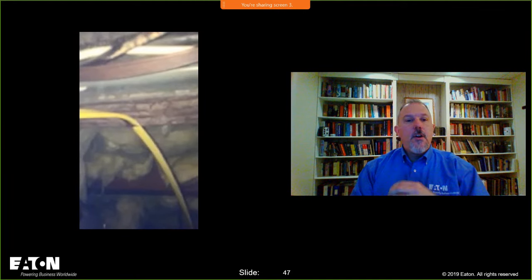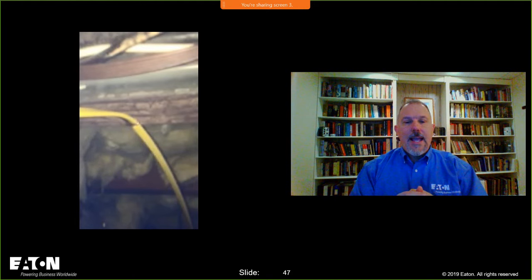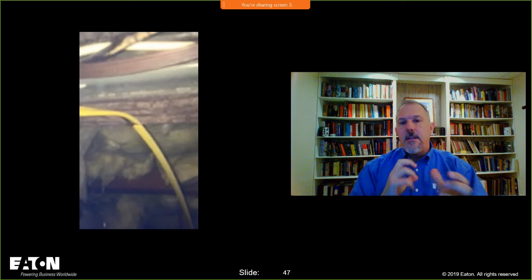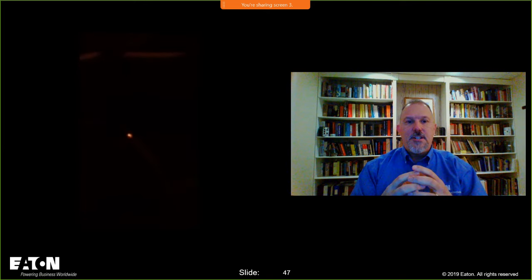This was a video that was sent to me of an arcing fault that was occurring at a staple. It's a little bit blurry, but they're going to shut the lights off in this video, and you're going to see the glowing connection where that staple has penetrated and caused an arcing fault inside of that equipment or in the circuit. This was at a joist stud.